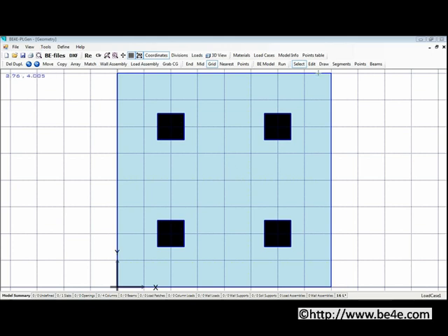So first of all, I'm going to select the draw mode, and then make sure that you snap the grid. I'm going to draw a wall. I'm going to go to select mode and right click and select it as a load patch. Click OK. Now, to see the number of divisions in the PLGen, you can simply click on the button near divisions. Now, as you notice, it shows you NA and NB as both equaling 4, meaning there are 4 divisions in the load patch.